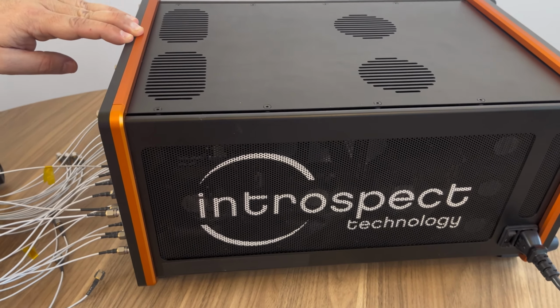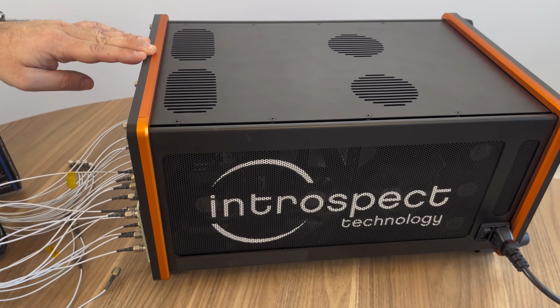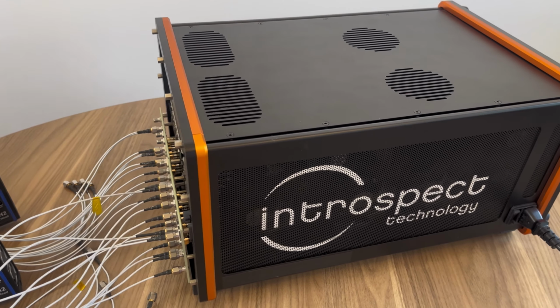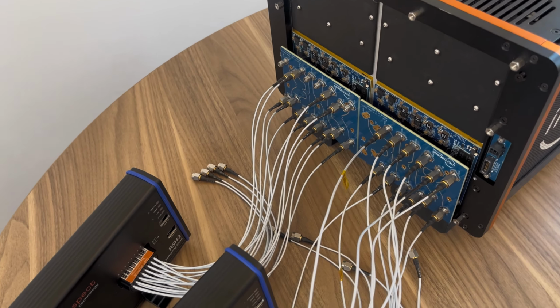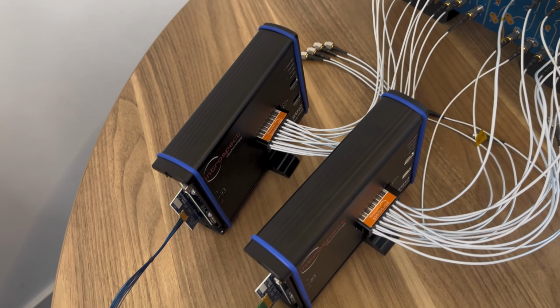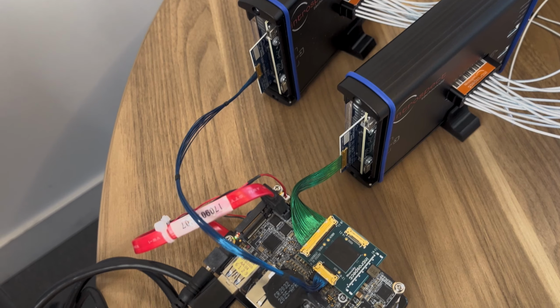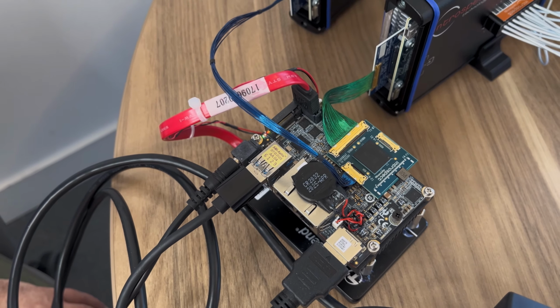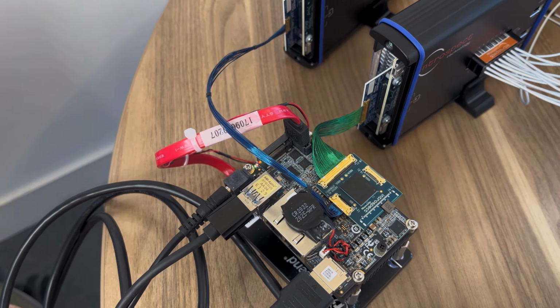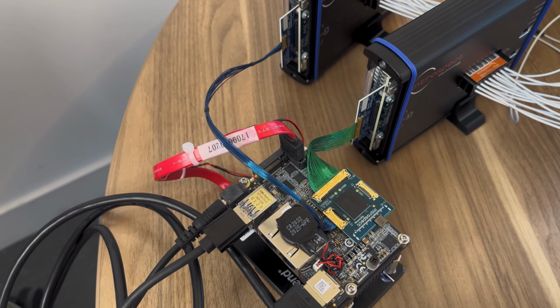This is the latest product from Introspect technology, and it addresses the highest speed applications for memories with a high sampling rate, with advanced features like supporting clock stops and clock frequency changes, and unterminated CA operation, as well as nested triggers and nested commands for different applications.